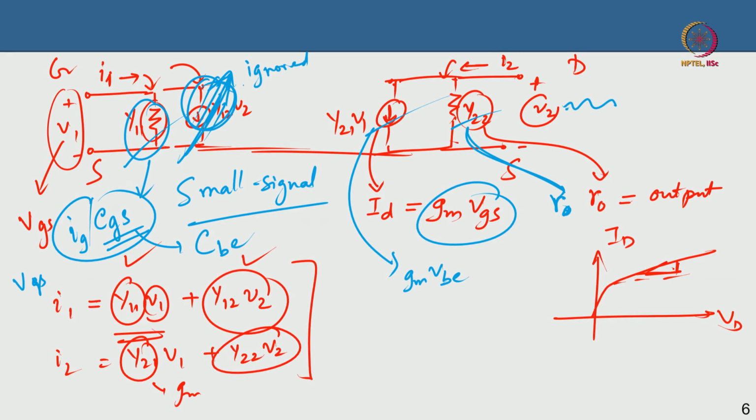So over to the whiteboard here. In the last slide, we saw that there are 3 components predominantly, the CGS, the output resistance and the GM-VGS in the small signal model, but in reality there are many components. So maybe it will be helpful if I show the physical structure of a transistor.